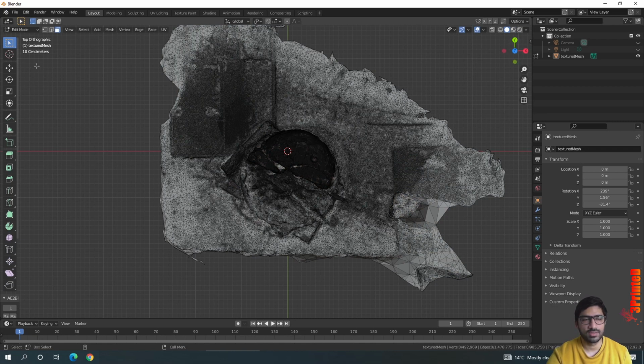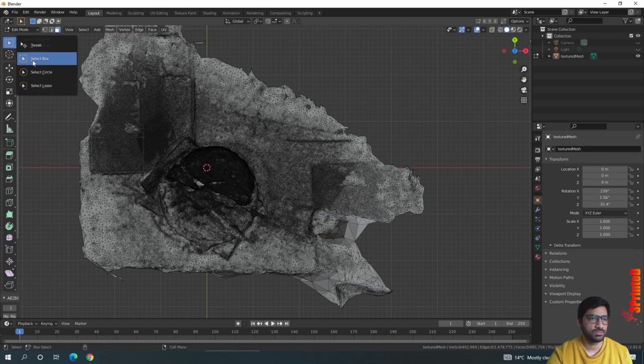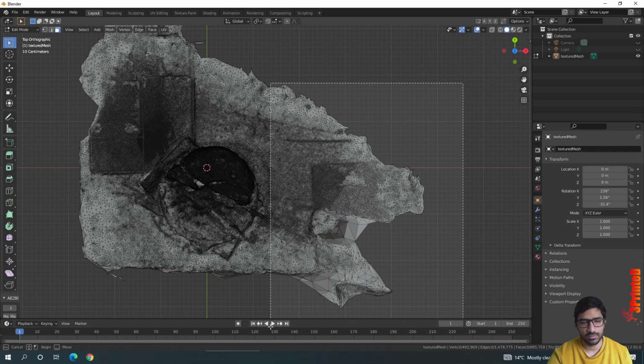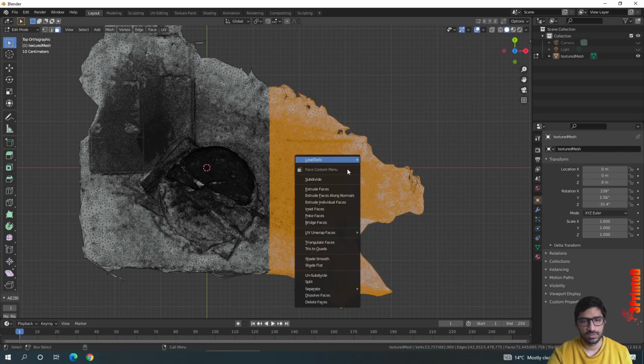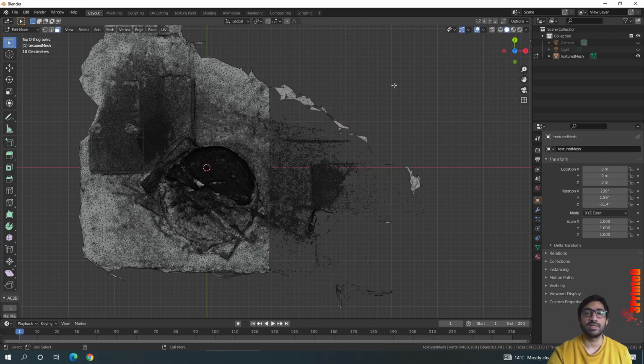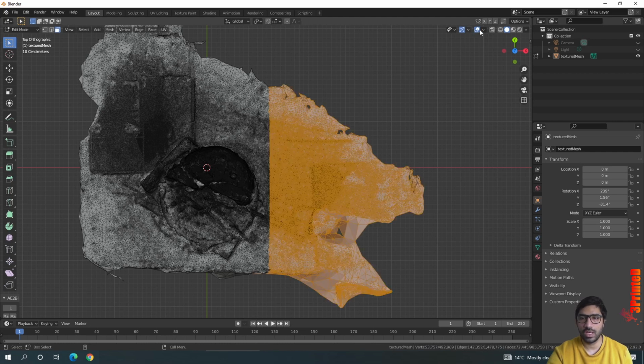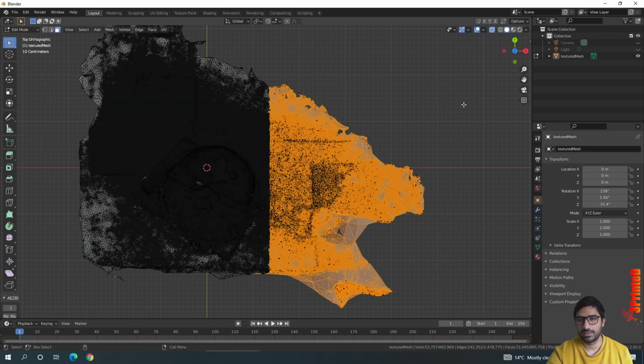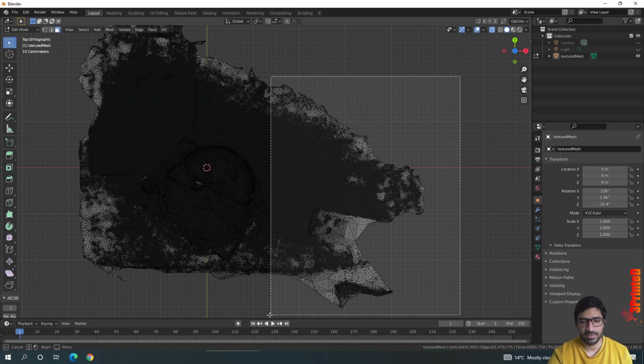Okay, go to the grayscale mode. It will be much easier to do the selection. First I will quickly delete the object, so I will just do this and delete faces after right clicking on the screen. See the problem, you still have the faces left. So to solve that issue, just come here on the top side of the bar, or you can press X to toggle this on. Now select again.